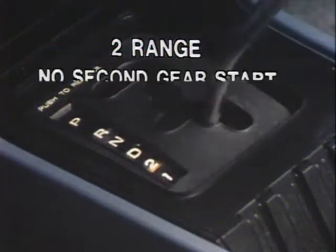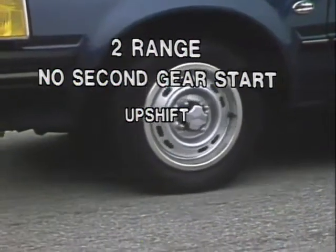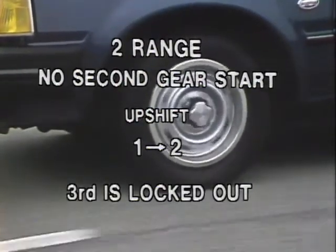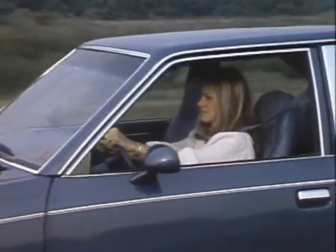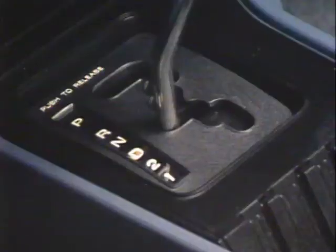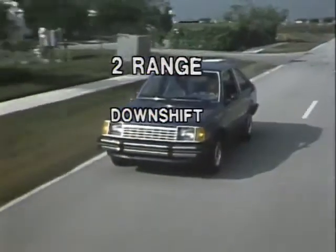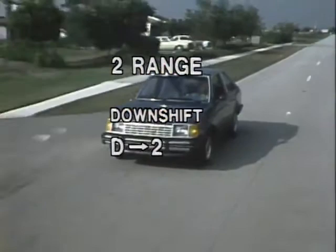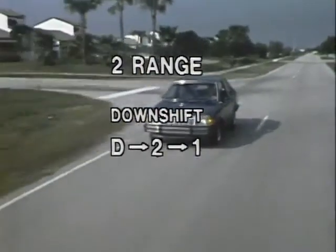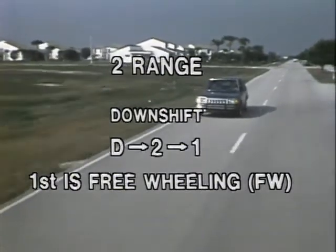In range 2, there is no 2nd gear start as in other Ford 3-speed automatics. The ATX starts in 1st gear and then upshifts to 2nd gear. 3rd gear is locked out by the hydraulic system. If the selector is moved manually from D to 2 at normal road speed, the transaxle will downshift to 2nd gear. As you coast down to a lower speed, it will automatically downshift to 1st gear. In range 2, 1st gear is freewheeling, the same as it is in D range.